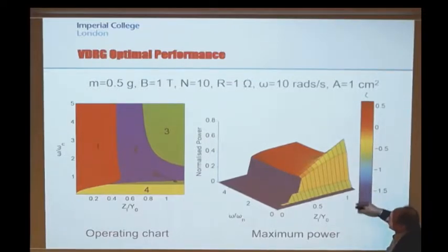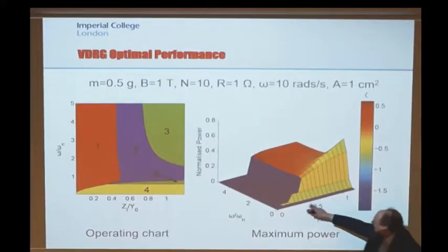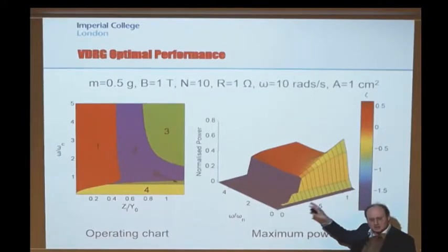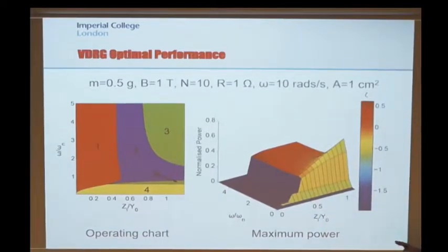If I operate with a device which itself is very small compared to the movement that is exciting it, then I'm ending up on this part of the axis. And you can see now a sort of direct comparison between where you end up on this graph here with the Seiko-Kinetic watch compared to where you might end up in a traditional modern-day vibration harvester. Because the Seiko-Kinetic watch is a device which is about that size, but I'm exciting it by putting it onto my wrist, and I'm swinging it potentially through quite large movements.